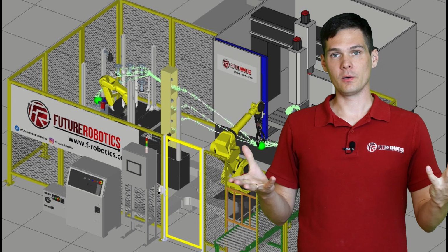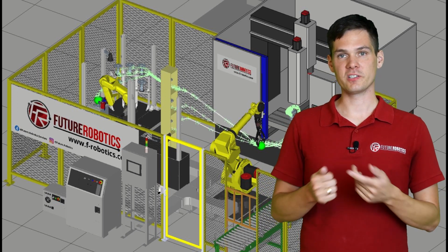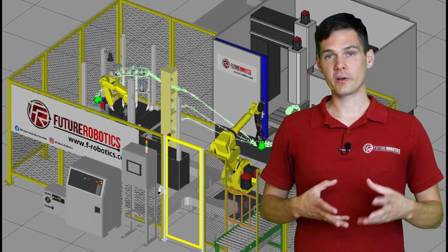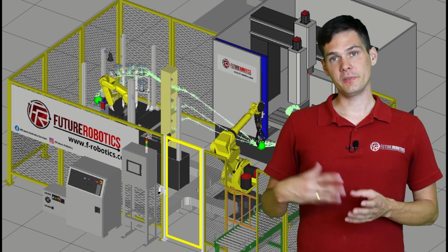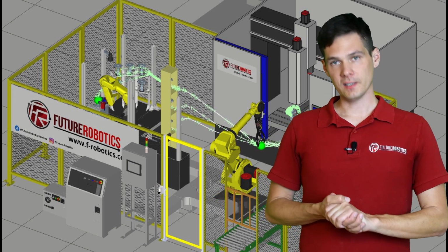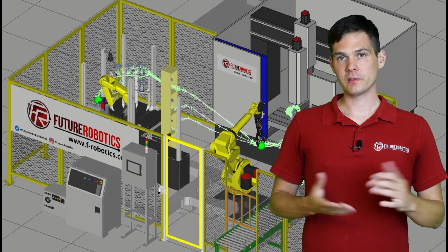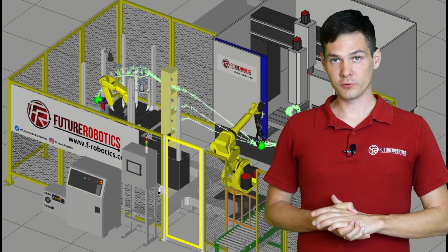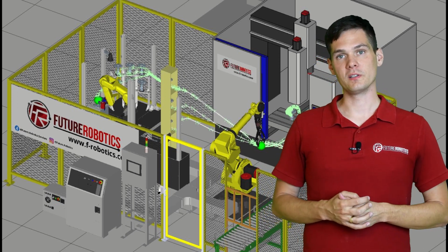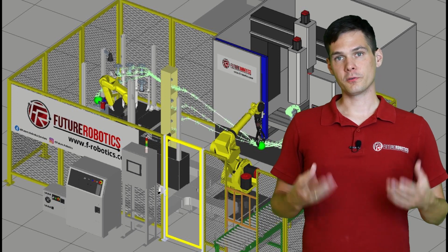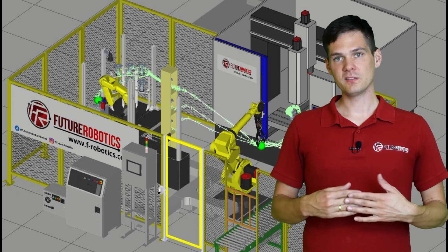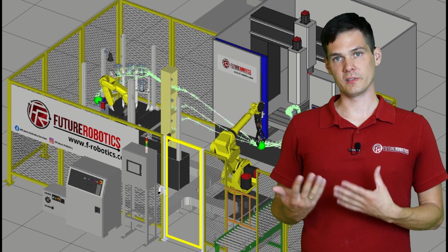Probably you're going to ask, okay, we can use other things for it, like handshakes, we can use different programs, and we can let the PLC control the zones. Yes, you can. However, the general rule that I try to follow, and I will encourage you to follow, is whenever there is a possibility of two robots meeting in one place, you should use a collision zone there.